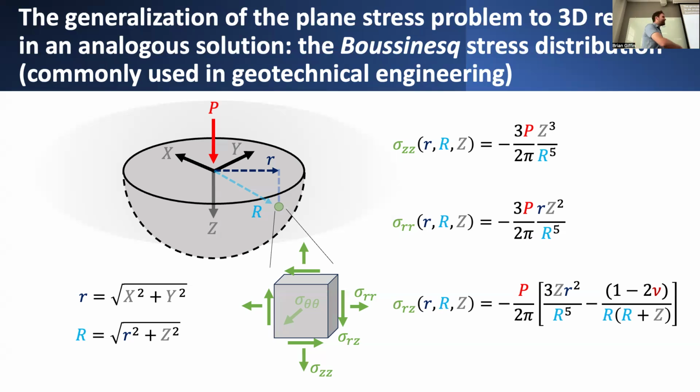And we'll talk in more detail about specific ways of assessing, well, at what point will this local chunk of material undergo some shear failure? In general, it'll depend on, yes, the amount of shear load that's being applied to this small chunk of material, but it'll also depend on how much that chunk of material is being compressed. So it's actually a pressure-dependent shear failure mode.